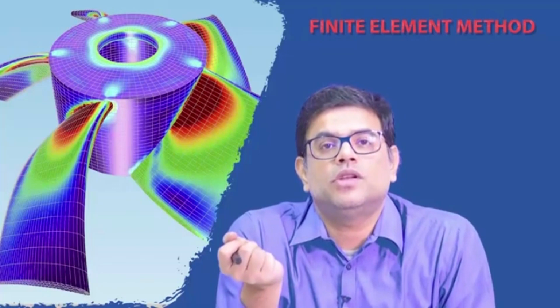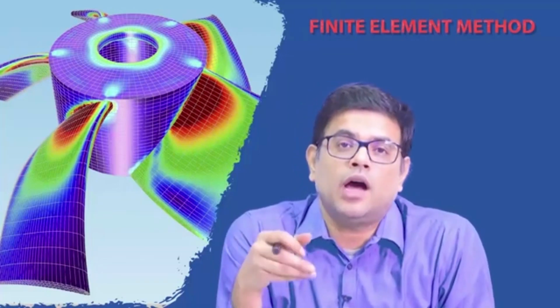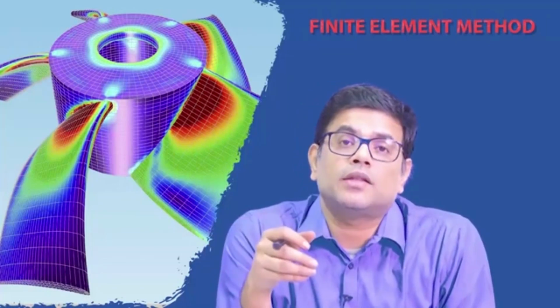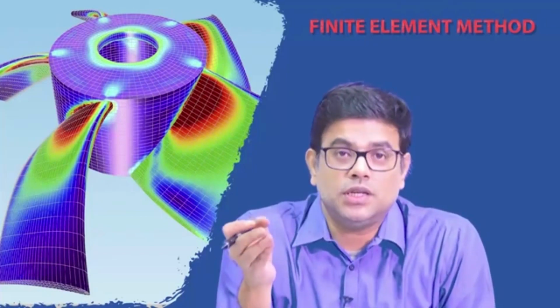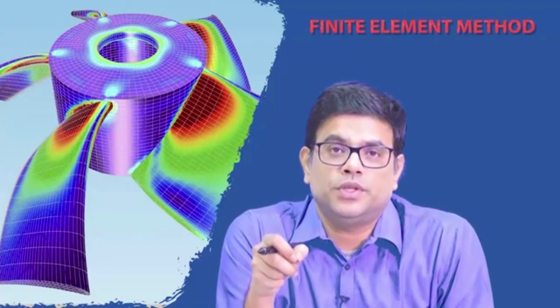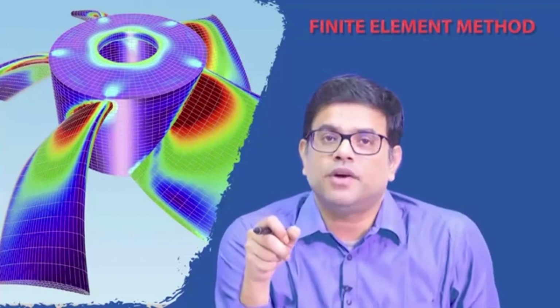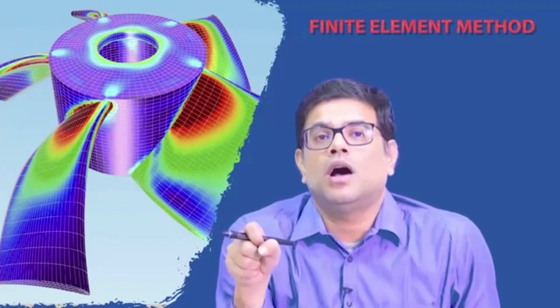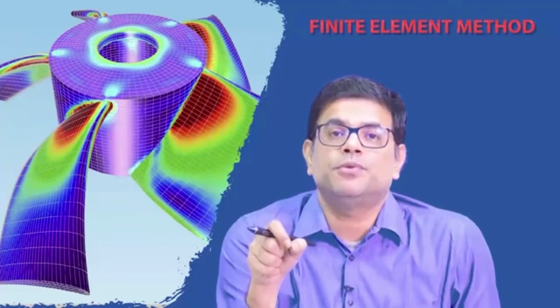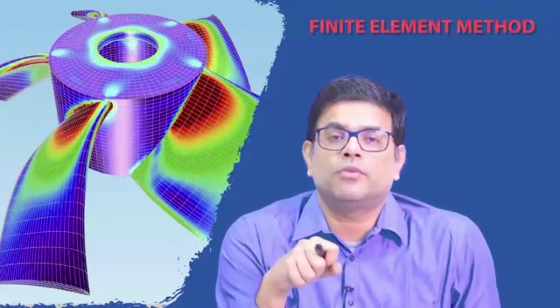In general, the weighted residual method requires higher order differentiability, and the weight function need not satisfy the homogeneous boundary condition, but keep in mind that the approximating basis functions need to satisfy the homogeneous boundary condition at the boundary where the field variable is specified. So this is the main distinction between the weighted residual or Galerkin method and the standard weighted integral statement based on the Rayleigh-Ritz formulation.